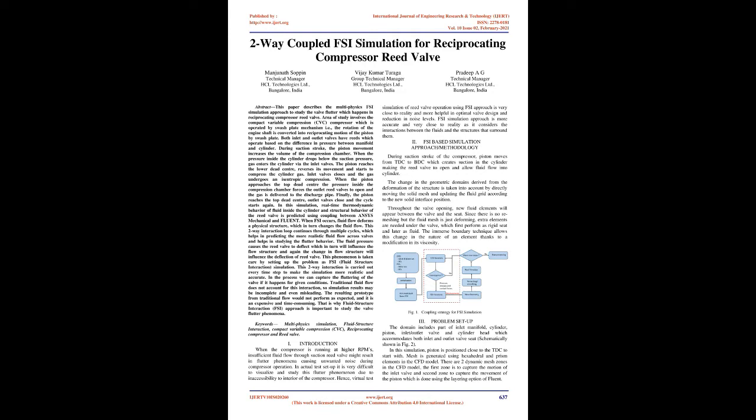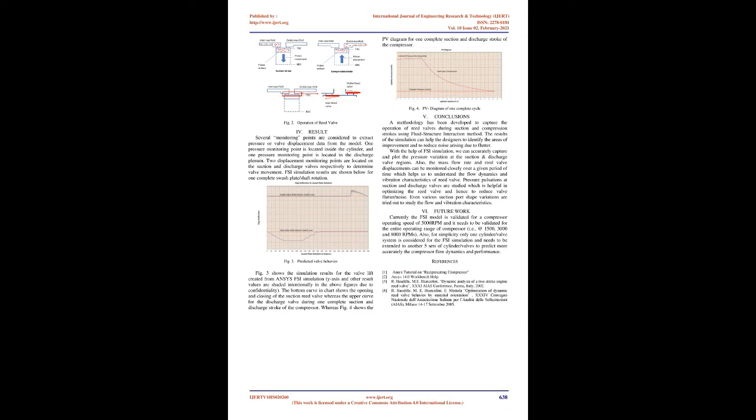FSI-based simulation approach/methodology. During suction stroke of the compressor, piston moves from TDC to BDC, which creates suction in the cylinder, making the reed valve open and allow fluid flow into cylinder. The change in the geometric domains derived from the deformation of the structure is taken into account by directly moving the solid mesh and updating the fluid grid according to the new solid interface position.